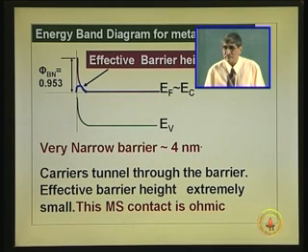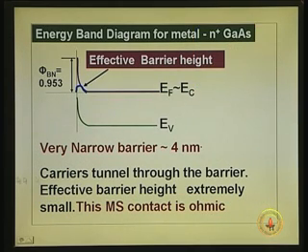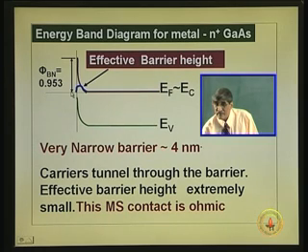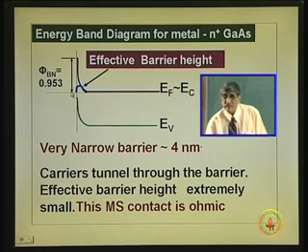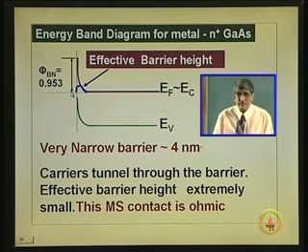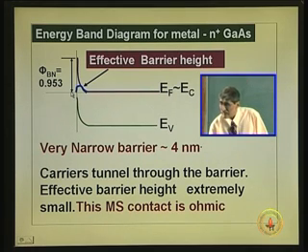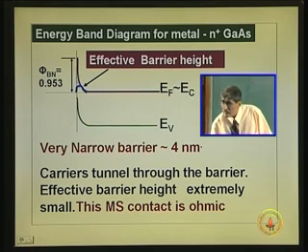That is the diagram now. So, the depletion layer, you see, is decided by that variation. Potential is still 0.953, that phi B n, which you see. So, apparently it looks as if the barrier height is 0.953. But now what is happening is, the maximum width here is actually 4 nanometers, that is what we have calculated.